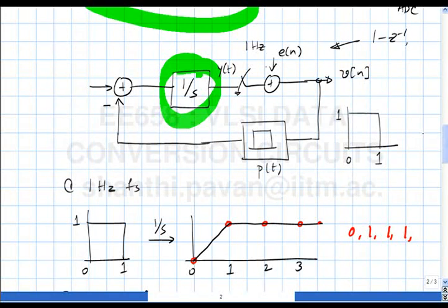If given 50 Hertz and times 2 pi and all that, forget about it. There'll be only completely crazy results. Okay, so carrying all these numbers doesn't make sense. But you know that real frequencies are much higher. That doesn't remove any glory from the theory, right? All that you need to do if you want to make this network have the same behavior but at some other frequency is to simply scale all the element values by the appropriate number. That's called frequency scaling, that you know already.